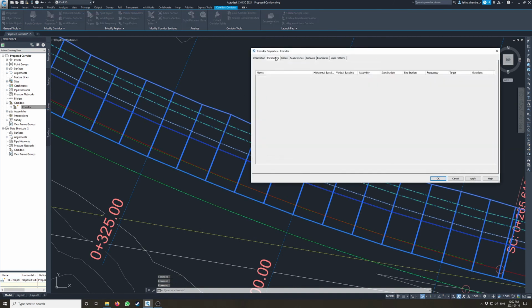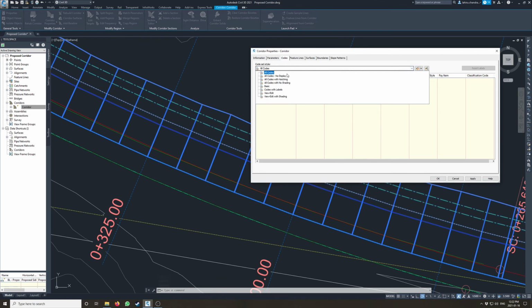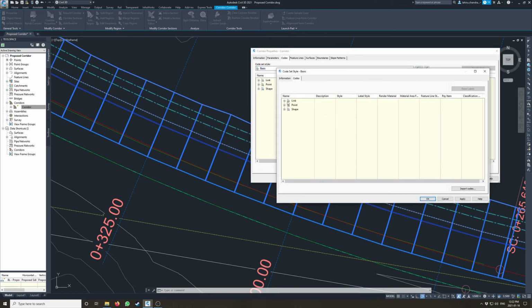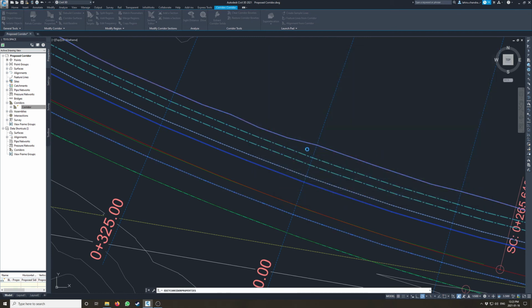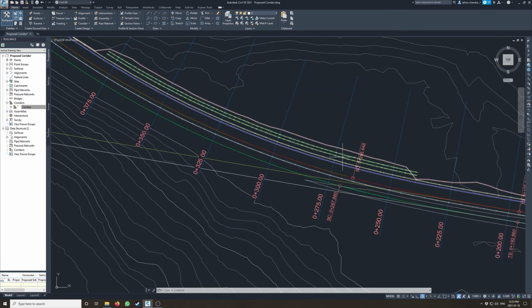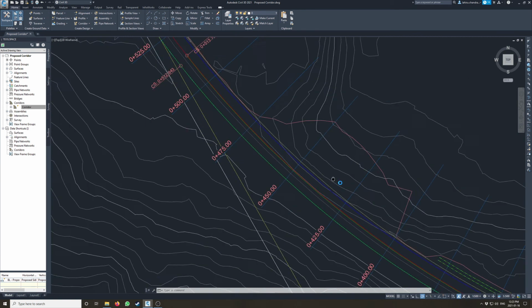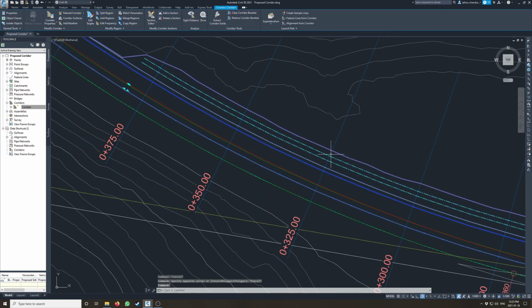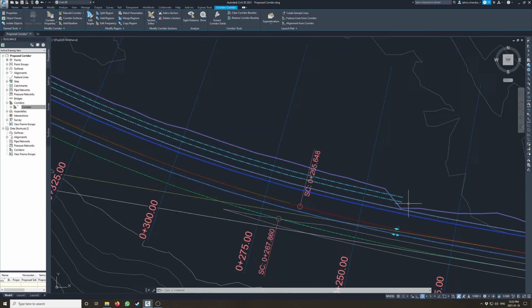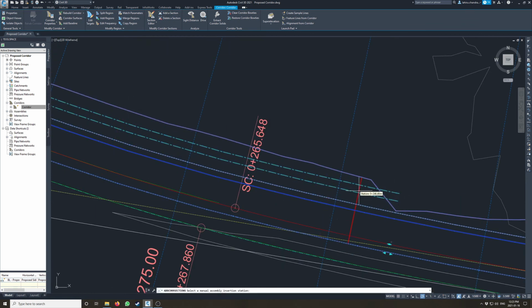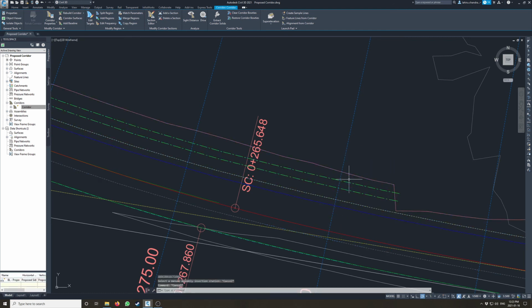And then another thing you can do to make it look nice, let's go to basic. We can turn off the links. So we can turn this off to no display, hit OK, and now you can see that your corridor looks a lot nicer. You probably want the links if you're still working on your corridor, like you want to see where your sections are taken, or you might want to create an additional section here just to make this transition smoother. So like I can do that and that and that. Yeah, just to provide some additional definition.